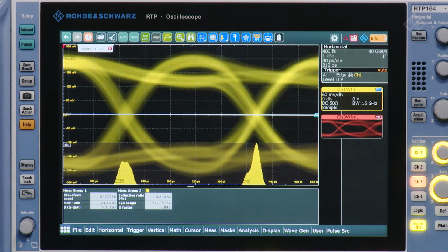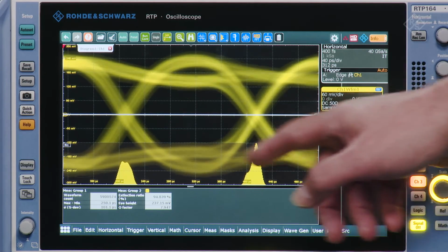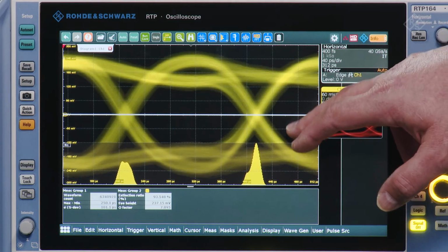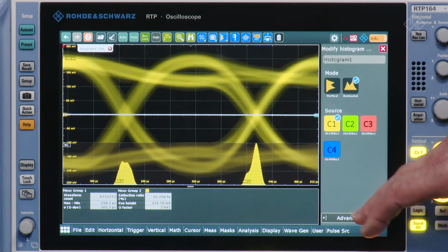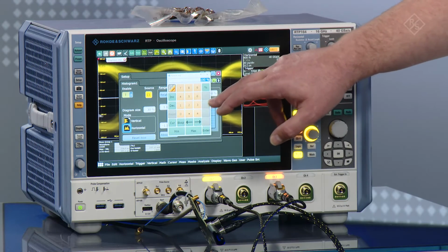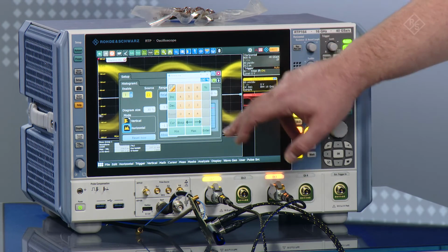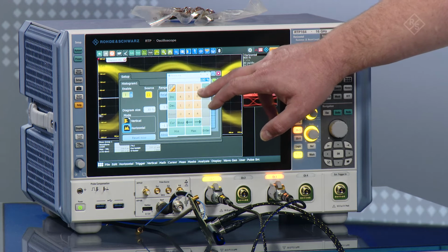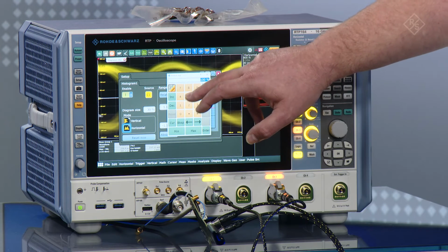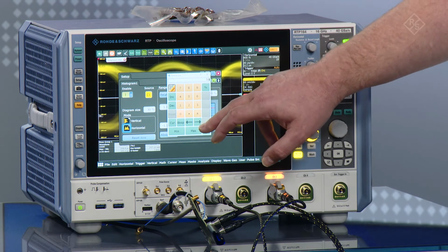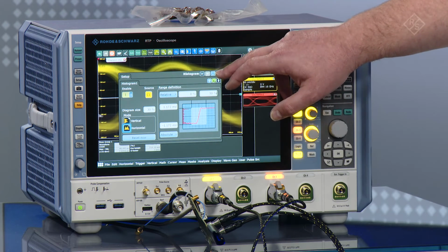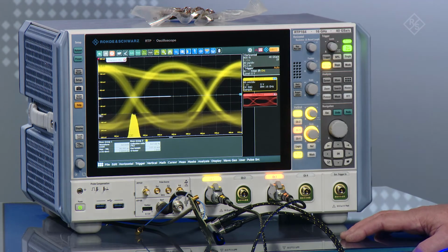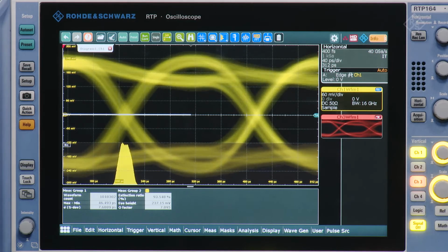In order to get a meaningful measurement, because you see the histograms are different, I have to change the histogram a little bit so that I basically have just 50% to capture just 1. But the important message here was already that the histograms on each edge were different, which is sort of an inaccurate measurement. So here you see a sigma of about 7.6 picoseconds as a variation. So this was the standard case.